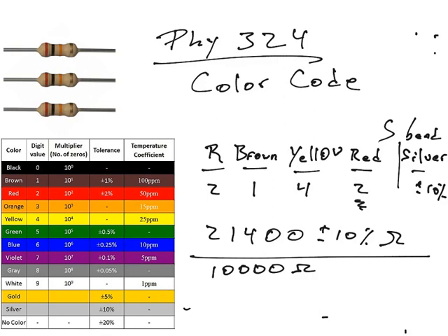So what colors should be on this resistor for it to be a 10,000 ohm resistor? Well, if it's a 4-band, I have 2 digits I know. The first digit is a 1, second digit is a 0, and then we have the multiplier, which is how many zeros come after those digits. In this case, it's a 3. And so I better find a resistor whose first color is brown, second color is black, third color for 3 is orange, and then whatever tolerance it is we have, a gold stripe or a silver stripe or whatever it is for the fourth one. So if I want a 10,000 ohm resistor, I need a brown, black, orange. If I want a 20,000, it's going to be a red, black, orange, and so forth.